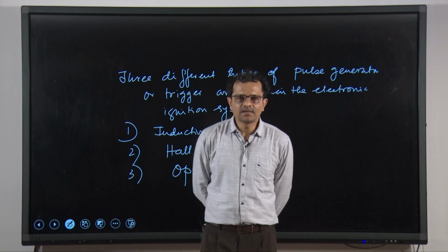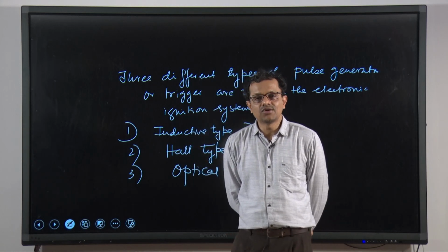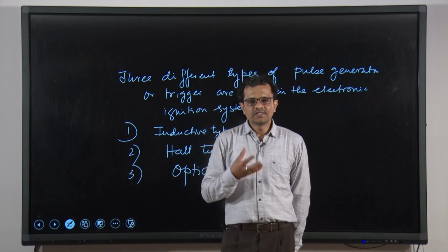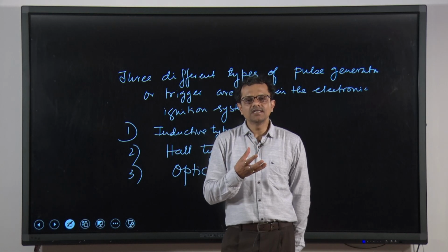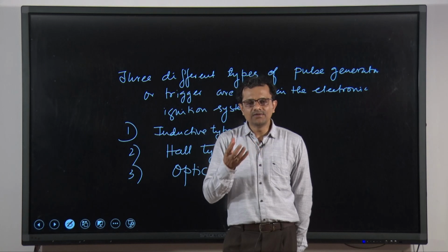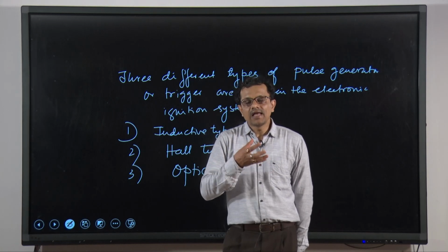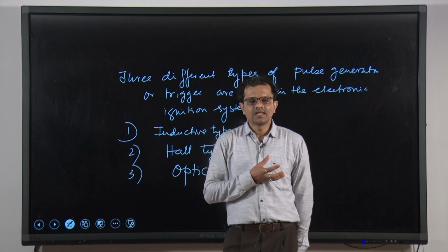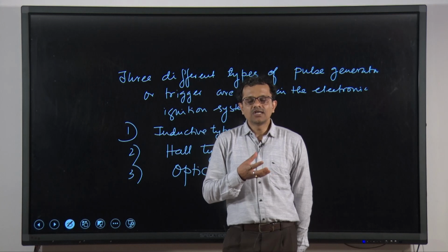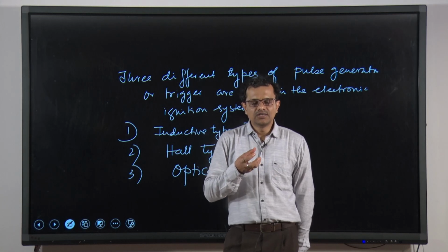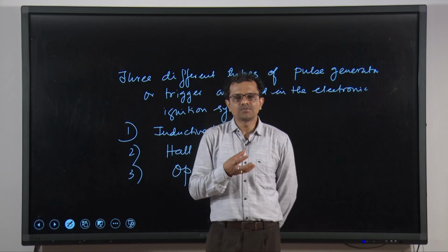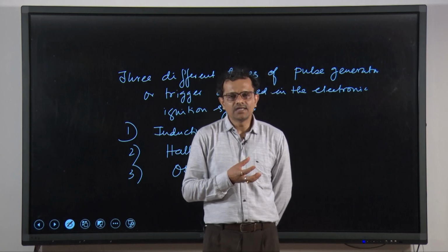Thereafter, we have discussed the limitation of this particular system in the context of variable speed engines, and also the present requirement of transitioning from stoichiometric burn engine to lean burn engine, which necessitates some amendments. Those challenging aspects are not possible to overcome using a battery ignition system.